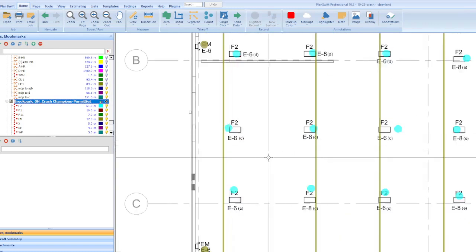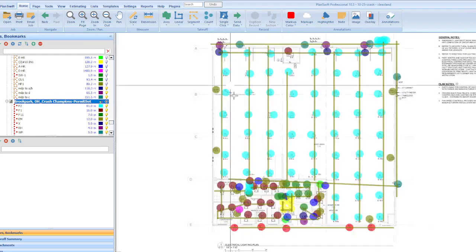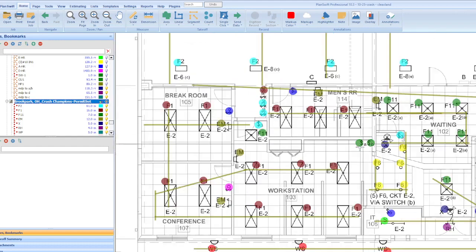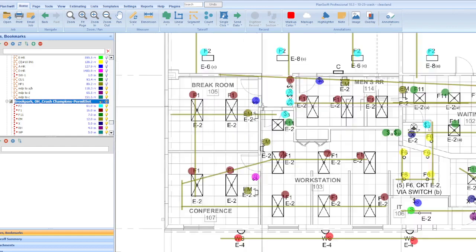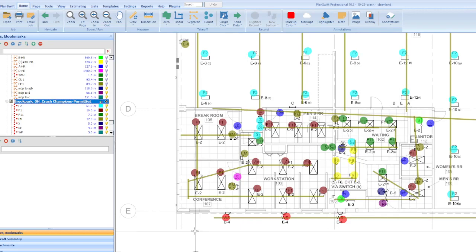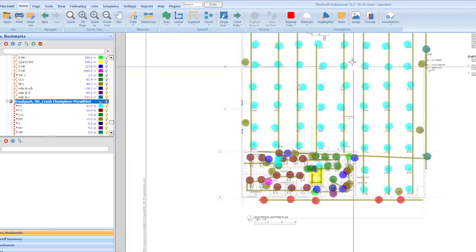You know that they're going to E6, every other one, E6, all of these are going to E6, so you want to maybe put a little more diagonal, add 10 or 20%. Because you want to give a good representation if it's not already given. Because we know these two are going to the same place and then going to that, and they're all going to be connected. And so you want to do your best to give it a good representation of how the electrician may run the wire. And then I think we added like 10 or 15, 25%.